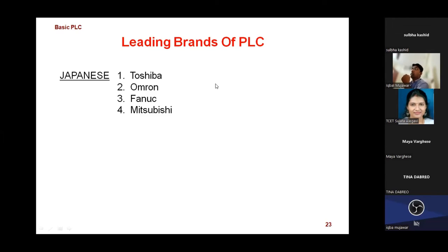If you want, you can go and purchase. The only drawback is, as I explained in the video, the ladder coding, the addressing style, the style of the codes, whatever blocks and symbols are there, normally open, normally close, timer, counter, is a little bit different. It's not that difficult. Everyone can understand; only some initial time is required. Suppose you're comfortable making code with Mitsubishi, you might require a little bit more time to understand Allen Bradley.